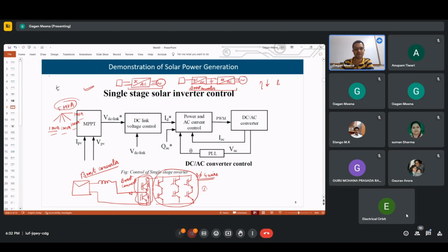Then cell and module balancing is another function. By monitoring these, we want to maintain the same voltages or SOC across all the cells to avoid thermal runaway, hotspot generation, and circulating currents.